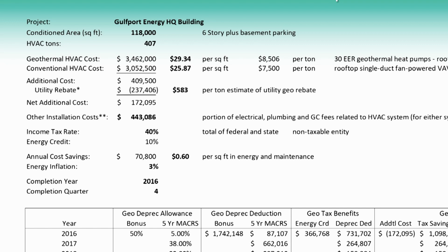So when you look at the economics, you're comparing the cost of solar and the benefit to just the grid electricity. With geothermal, you have a double benefit. You're looking at the savings of the energy, and you had to buy something. You have to have a heating and cooling system. So we're only working off a cost difference plus the energy savings. So that helps the economics look a lot better, because you have to have something. Now, that's not always the case.